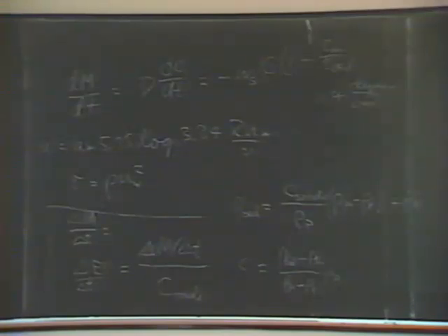Well, the methods of minimizing sediment into channels and harbor facilities really boil down to two approaches. The first one is, if sedimentation occurs, keep it moving on. Keep it moving through. You have sediment, one way or the other, just keep it moving through, and I'll describe means of doing that. The second one is keep sediment out. If there's some way that you can wall it off or divert it some other path, then by all means keep the sediment out.